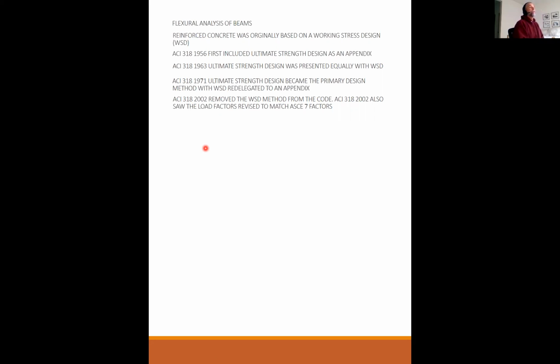I remember when 2002 came out, and that was actually pretty nice, because what was going on at the time is that various materials were using working stress design. Steel in the LRFD world was using factor design, but their factors were not the same as concrete factors. So you can imagine the headache, the nightmare of, picture a concrete column built on top of a concrete footing that has a steel column coming down on top of it. So the steel column has LRFD load factors. The concrete column, you have to convert them all over to ACI load factors. And then you go down into the concrete footing, and the soil is designed using working stress design.